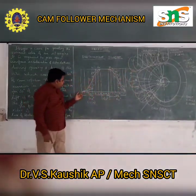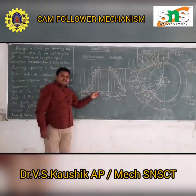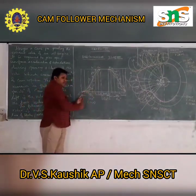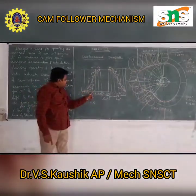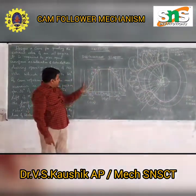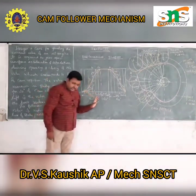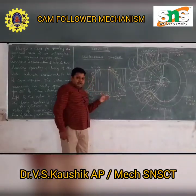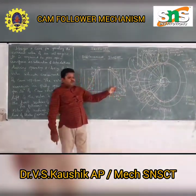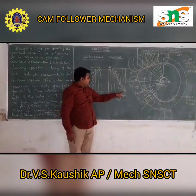Now you should draw the vertical. You should segregate this into 6 divisions. We should mark the points 1, 2, 3, 4, 5 and 6. You should divide this into 6 equal parts and draw the vertical lines. For the dwell, you need not draw anything. And coming to this, once again you should divide into 6 equal parts: 1, 2, 3, 4, 5, 6.